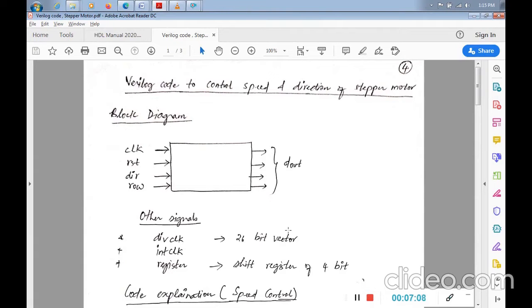Once we have the UCF file, we will save it. Once we save it, we will go into synthesis, then mapping, placement and routing, all these options. Then we will click on generate programming file. We will discuss it, and I will show you the video of how exactly it functions.